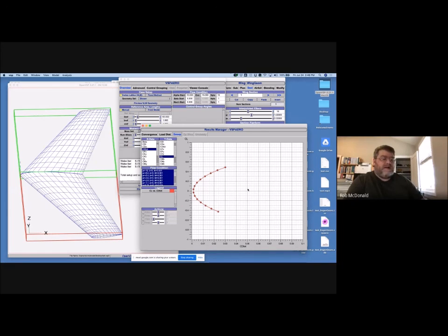I think that was really well put, and what we call that in aerospace is your ConOps. This is your concept of operations, and having a really well-defined ConOps and really understanding your ConOps is really important. Let me emphasize what you just said. You're going to take off from point A, and you need to get to an area where you want to patrol, and your sensor's not even on. You want to get there. Again, it's not about speed, but you want to get the range as efficiently as possible. So you're going to fly at the speed for best range over the area you're uninterested in, right?